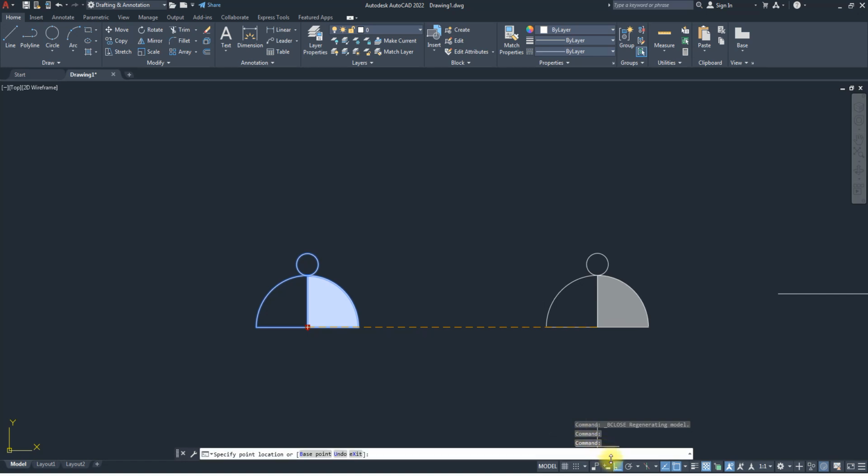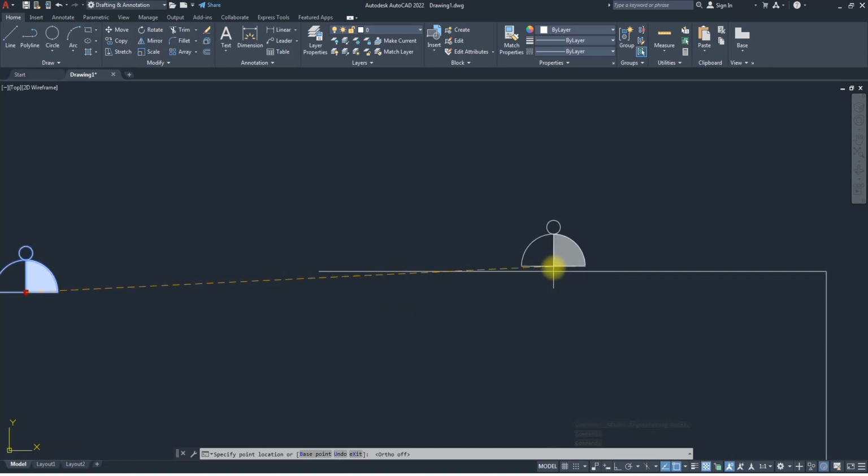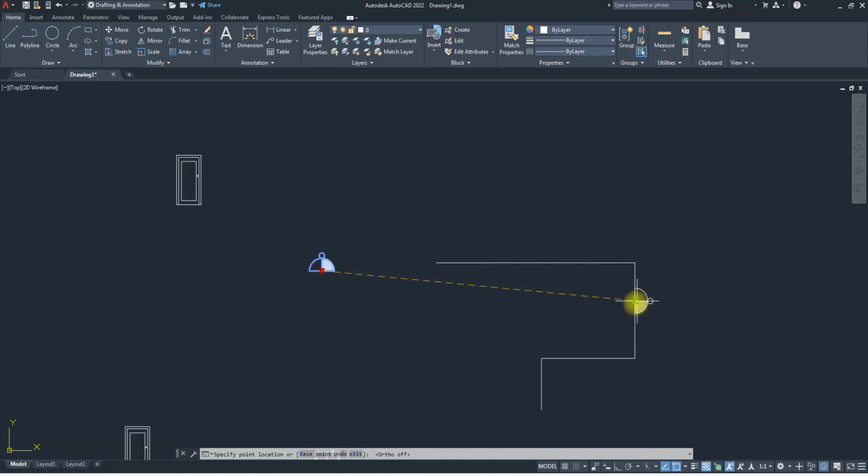So if I turn off my auto mode, I come to this place. Can you see this is aligned? If I come to this other side, I can flip to this side. If I come to this one, notice also aligned. Okay, so you can actually use it for all these electrical fittings, your switch, all these things. So any side you put it, it goes. You don't need to start rotating. So if I want it to go inside, I'll click, it goes inside.